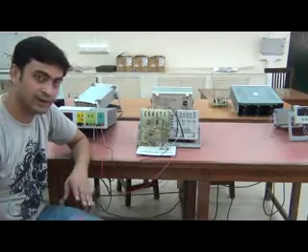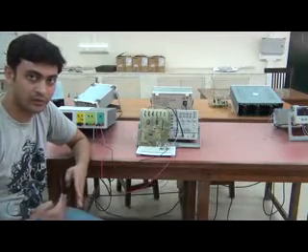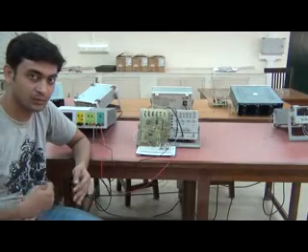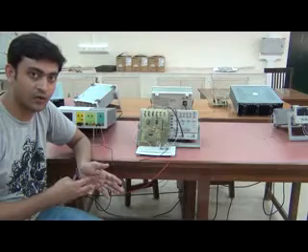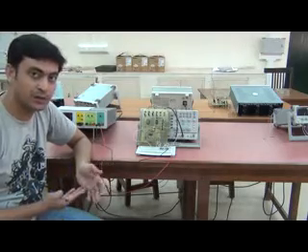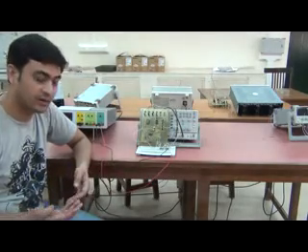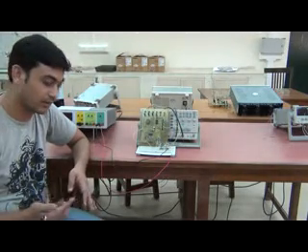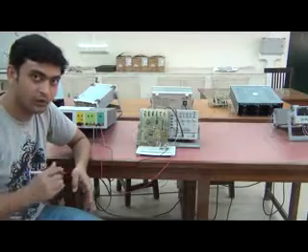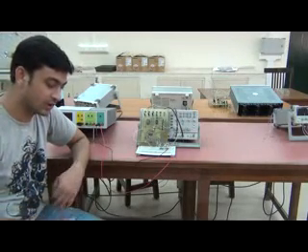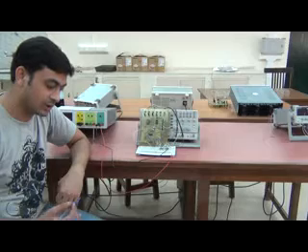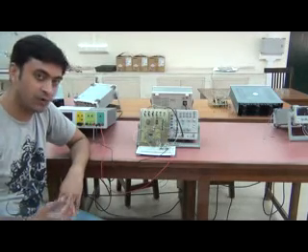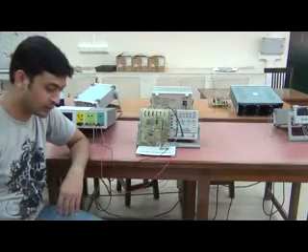So there is a direct relation between the number of sequence states required, or the number of representation bits for a sequence, and the number of flip-flops required. For example, for a divide by 16 counter we would have required 4 flip-flops, since we will have 4 bits to represent a sequence. Here the counter down counts from 7 to 0, starting from all ones to all zeros.